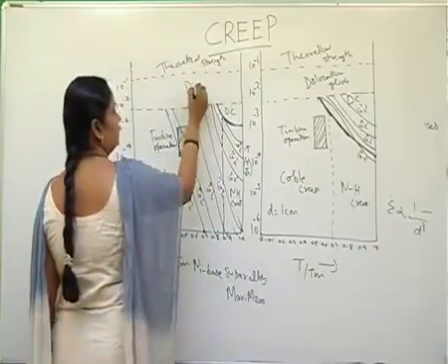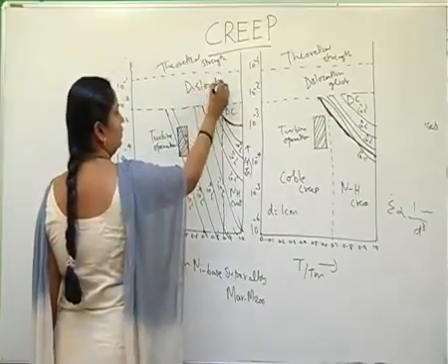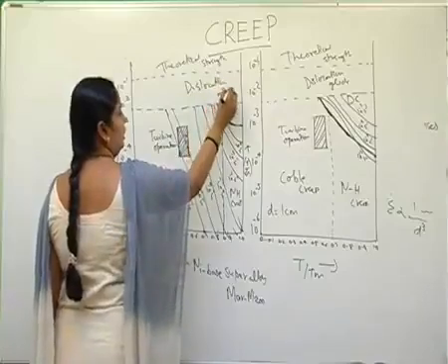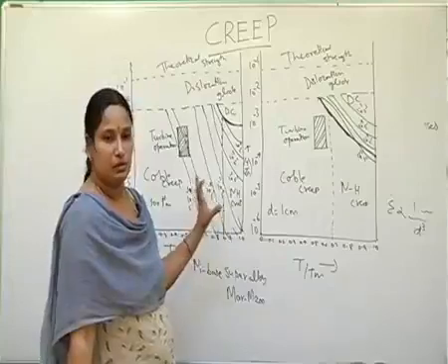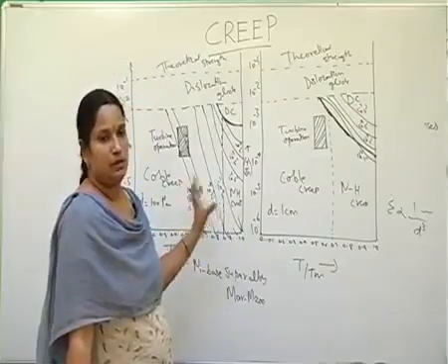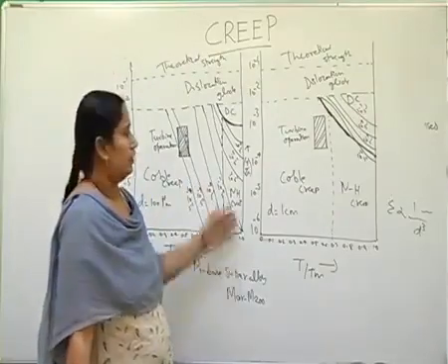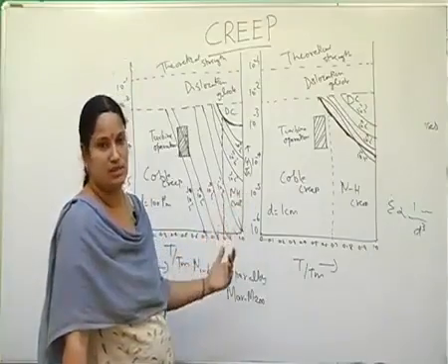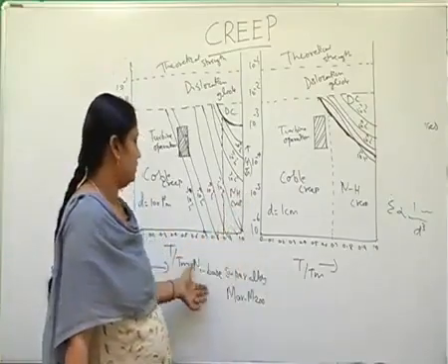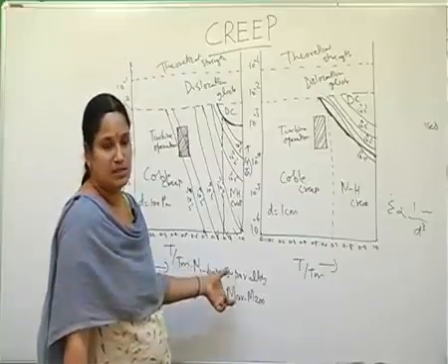Even though these two diagrams are not to scale, I want you to appreciate that by knowing the dominant creep deformation mechanism, one can design an alloy to be more creep resistant. So this is one example, for the case of a nickel based superalloy.